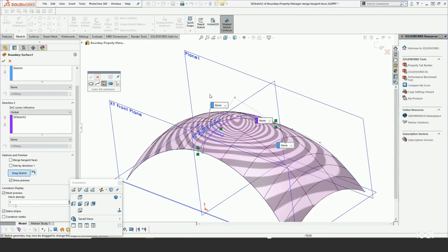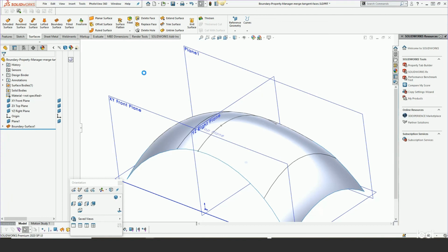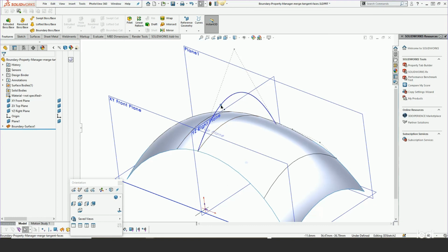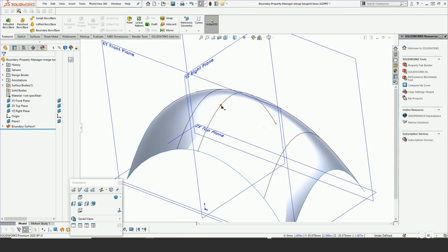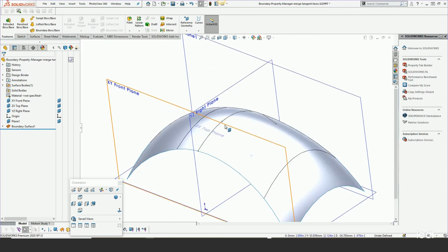It's rather limiting actually, because it only works for 3D sketches, and it only works after you've created it. I actually find in many cases it's just easier to have instant 3D on and just start modifying and then doing Control B to get the rebuild. And that can work for both 2D and 3D. So it has some uses, but I find myself not using it that often for that reason.